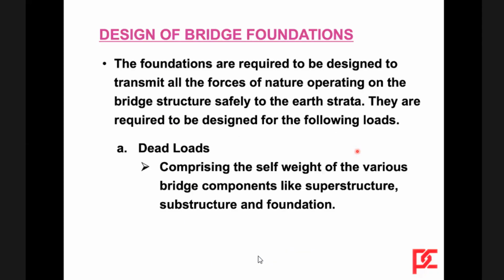Now that was just an arrangement of how the general arrangements were shown. Now we come to the design of the bridge foundations. Foundations are required to be designed to transmit all the forces of nature operating on the bridge structure safely to the earth. They are required to be designed for the following loads. Dead loads comprising self-weight of the various bridge components like superstructure, substructure, and foundation.